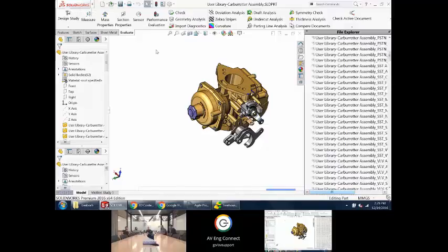So when you are working with stuff that is purchased or really complex multi-body type of thing, don't put it in as a subassembly. Do a save as part. When it opens up as a part, you'll have better performance. You can still have both of them in an EPDM system, an agile system. One's a SLD PRT, one's an SLD ASM.